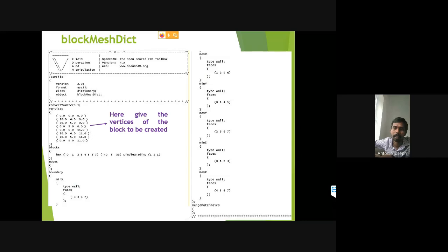Then again, what should I do? I should go to icoFoam or pisoFoam. Then again, I am thinking, what is the turbulent condition, whether it is laminar or turbulent. If it is turbulent, I want to use pisoFoam, transient and turbulent condition. If it is non-Newtonian or no Newtonian inflow, that doesn't matter. We can use pisoFoam. Now, suppose our case is transient, that's unsteady, and it's laminar, then that's okay, fine. We can use icoFoam.